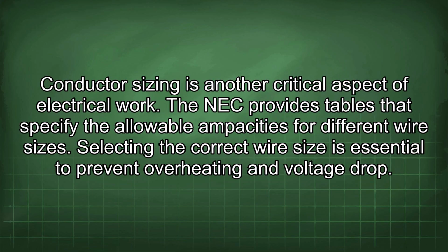Conductor sizing is another critical aspect of electrical work. The NEC provides tables that specify the allowable ampacities for different wire sizes. Selecting the correct wire size is essential to prevent overheating and voltage drop.